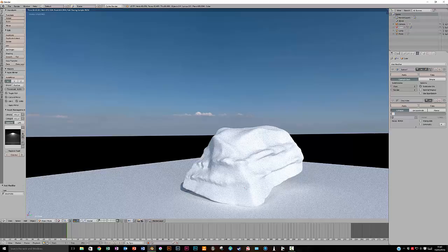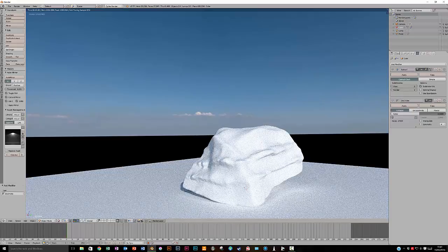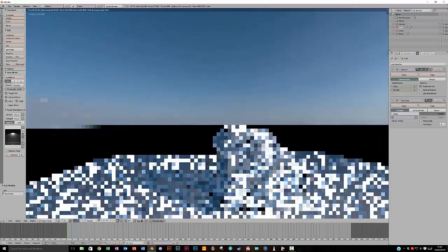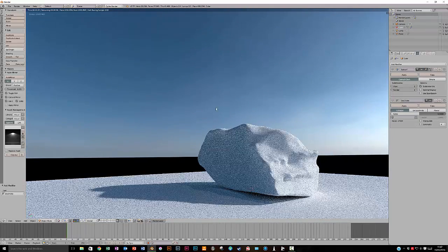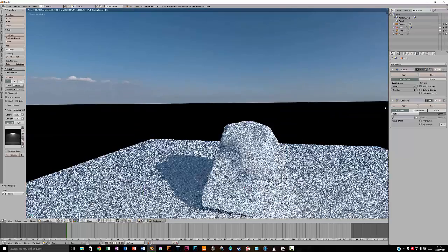But for instance, if I set that to 0.5, it's going to try and keep that shape as much as possible by reducing the number of polygons. Okay, we can't see any discernible change in the model, but we're now down to just over 40,000.